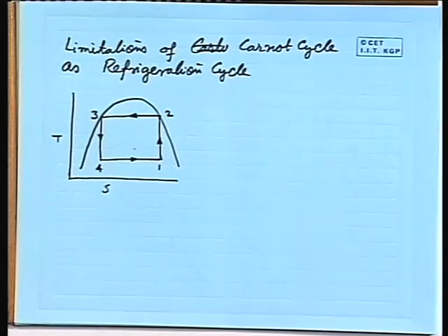Okay. And in a compressor, we know that in any practical compressor, if we have this type of design, the liquid refrigerant will collide with the valve and the piston head, and it will cause pitting and damage and all these things.